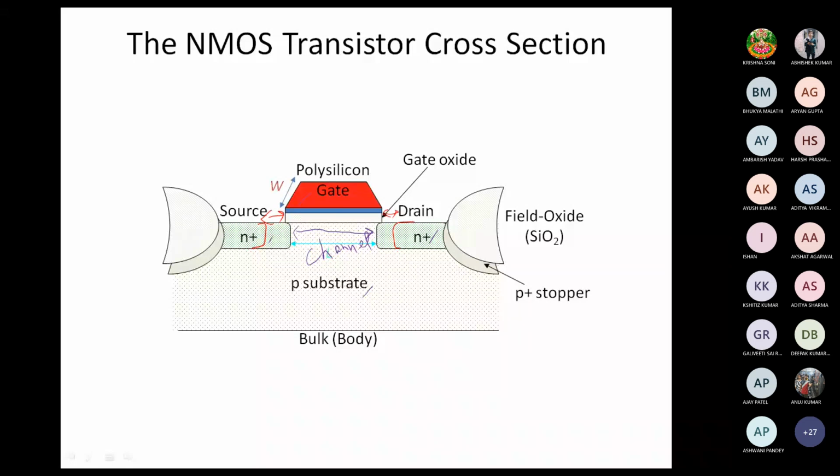When a part of the gate and source or drain overlap, that is called overlap, or if they are a little bit away from each other, then that is called underlap. So we may have underlap transistors or overlap transistors like this. Whatever the case, the difference may only be a little in the threshold voltage and other things. That is actually from the device part.